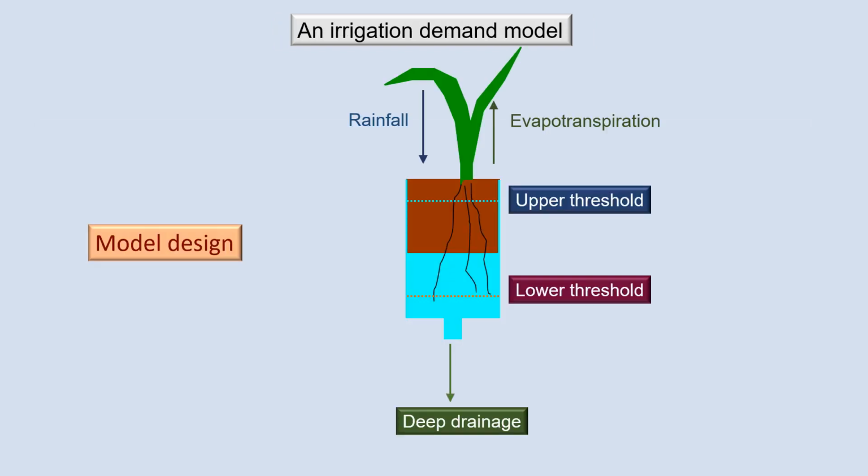This is a model that I built many years ago to look at the issue of irrigation demand. It's a simple model built around a soil moisture store. And this soil moisture store is present in many models, rainfall runoff models, land use models, so it's not an uncommon modelling device. The soil moisture store is filled with soil, a porous medium. The more water that's in the store, the more rapidly can water drain from the store. So there's a nonlinear function which relates rate of drainage to soil moisture content.